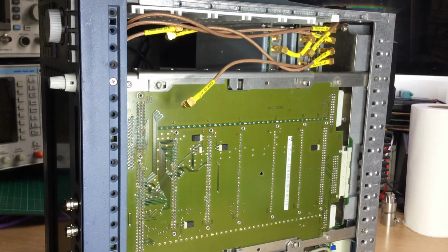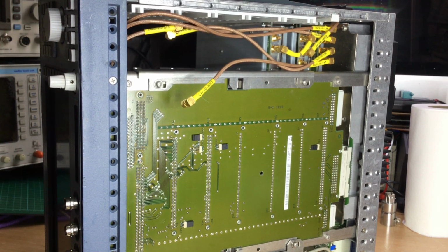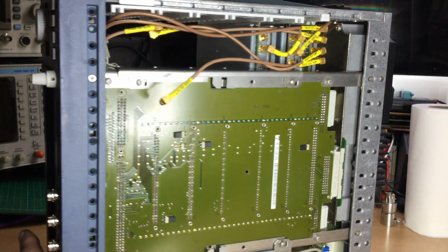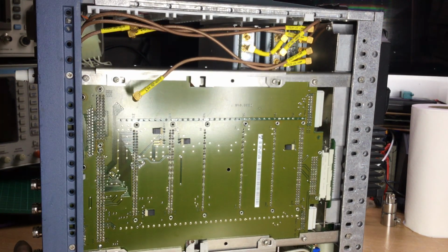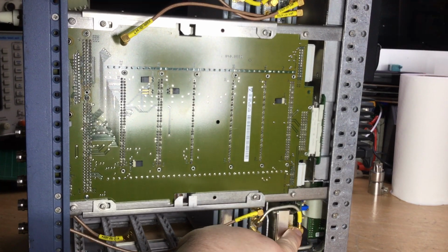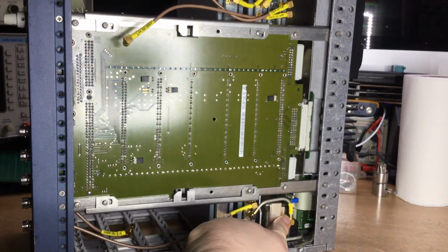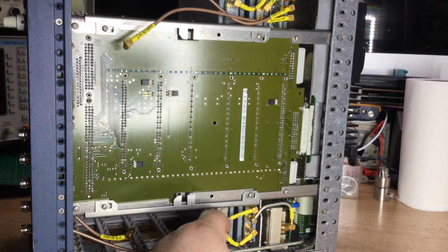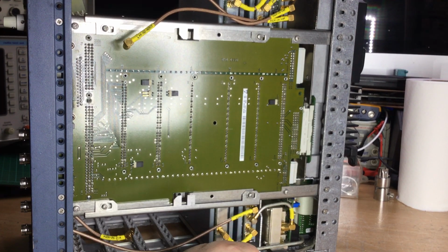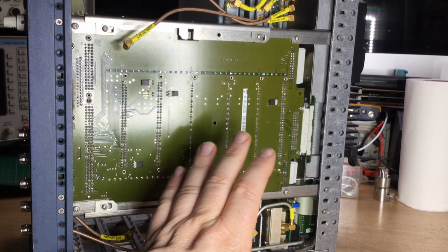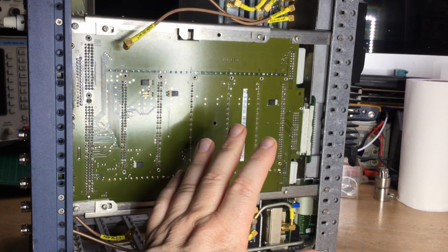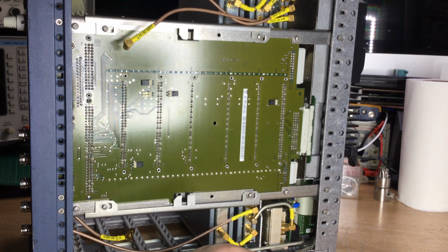Now, I can actually show that in better detail. I have a box of SMB and SMC adapters, so I'll be able to show you the differences. But that's just something to watch out for on these test sets. There is obviously SMA connectors as well, which is this one here at the bottom of the picture. That's an SMA. You've got SMC, and then the rest of them tend to be SMB. And that's quite common on nearly all Rohde Schwarz products, is SMB connectors. But it's always worth knowing that, obviously, if you need to make test leads up and things like that.